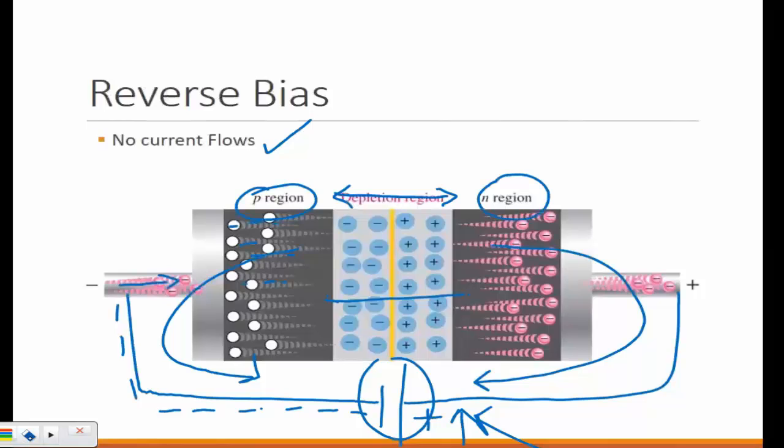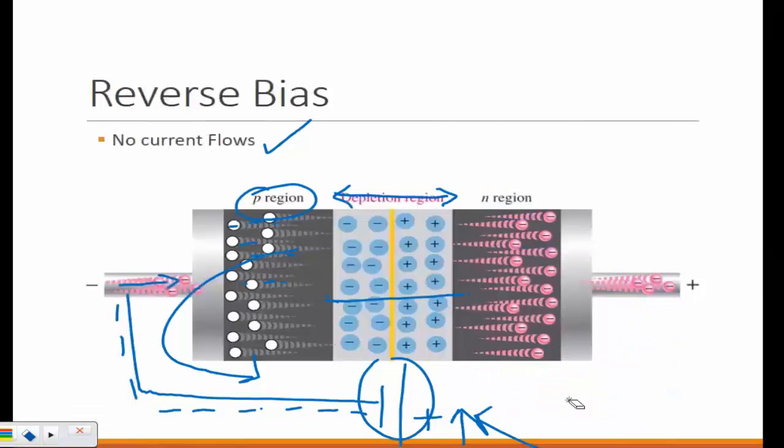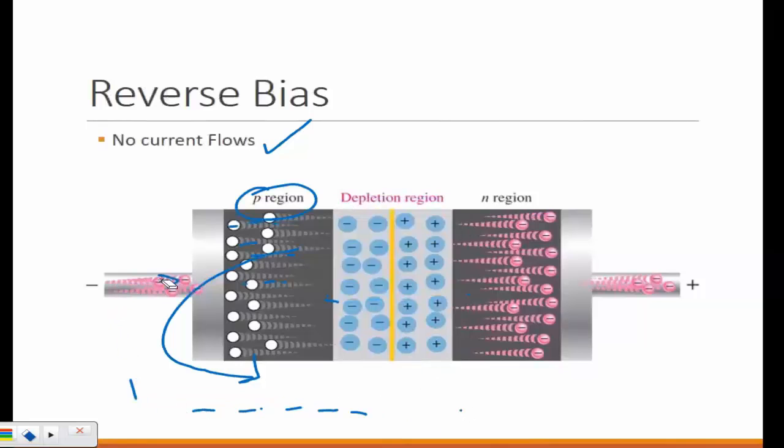The circuit though goes from positive to negative. So if you only want the positive half, you have that diode in there. It only allows the positive half and blocks all the negative voltage. Now you've got nothing but positive voltage. So in the applications, you will see where this behavior is more useful, right? So this is how it behaves, but maybe once we start talking about applications, it will make more sense in terms of how I can use this.